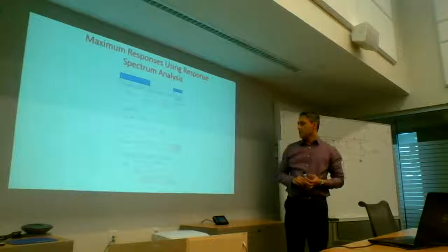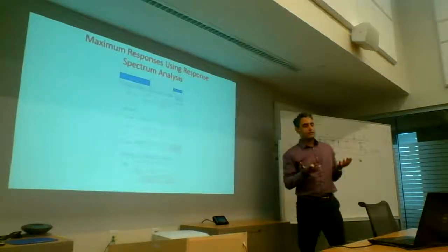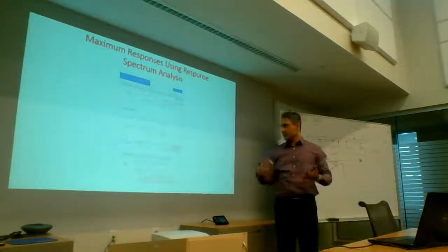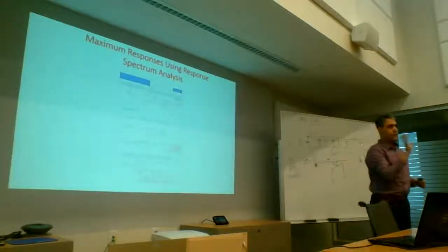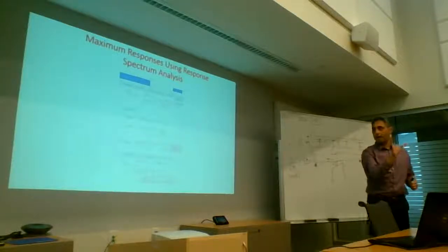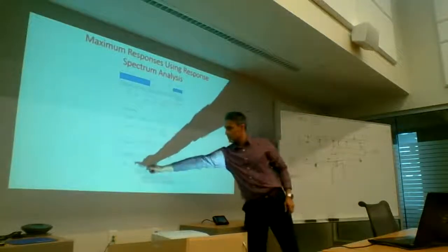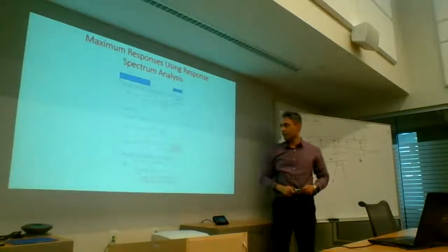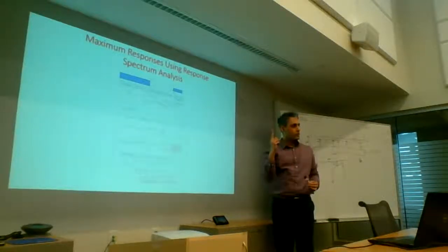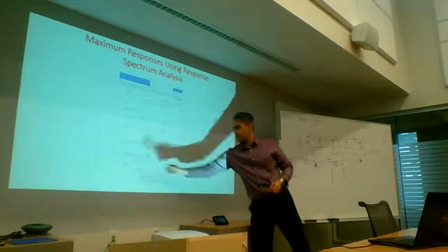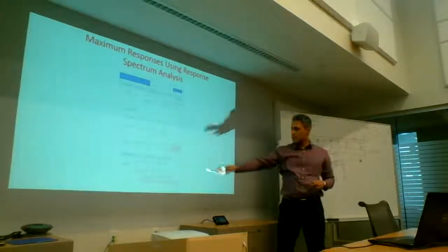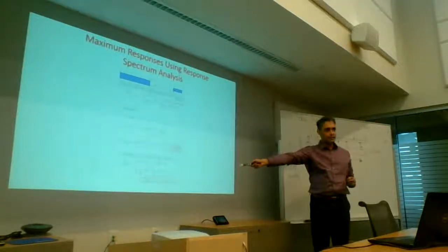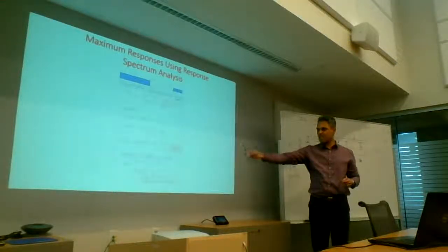So that's for each level, and similarly you can come up with your maximum U2 at each one of the levels. So now, if I were to use absolute values, I can just sum them up. This is for example, I've done this. You see how this bridge is primarily behaving in the first mode shape. Why do I say that? This is the displacement at the first degree of freedom due to first mode, maximum displacement, 61 mils. The maximum displacement due to the second mode is not even 4 mils. Same thing down below, 99 and 2 mils. So in this case, it's trivial.